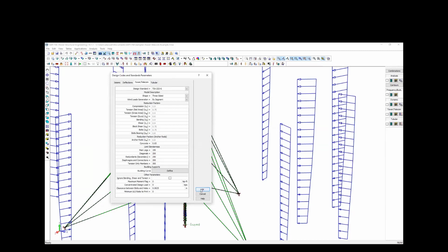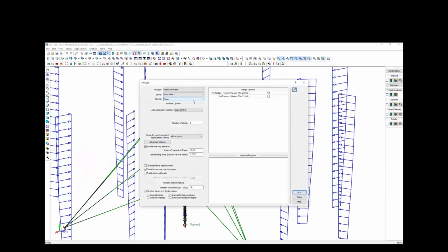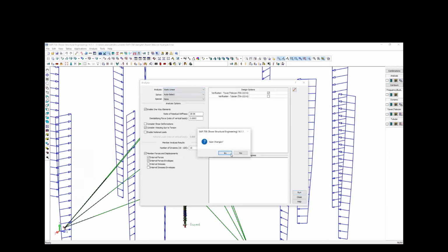When you uncheck it and run the analysis of this model, even if it should be a nonlinear analysis, just to see the results quickly, you can display the other limit states, including bending, shear, tension and bending, and compression and bending.